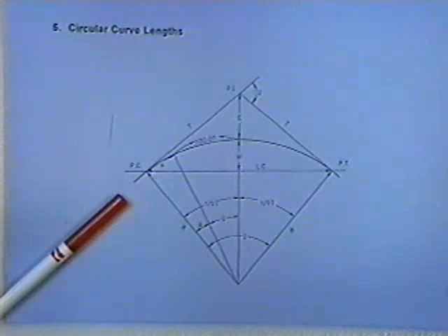We typically have tangent sections of roadway, and that's what the T would represent in this particular diagram. You might also pay attention to the following page. It has a lot of these acronyms defined, but I want to talk about them just a minute. We have our tangents, designated as T, and you'll notice a couple of points on that curve: PC, PI, and the PT. I'll talk about PI first.